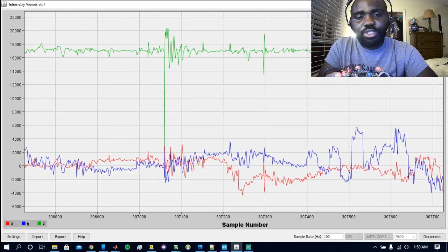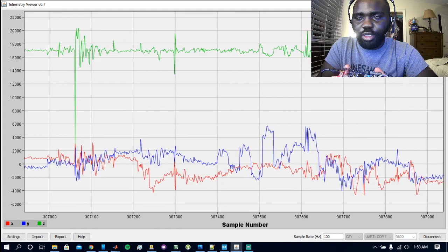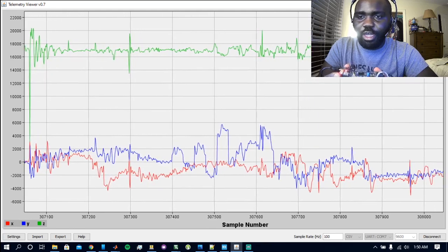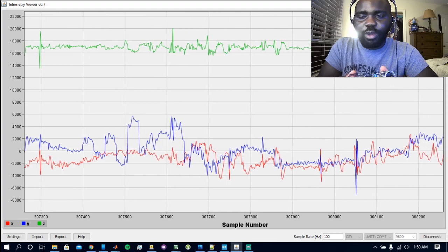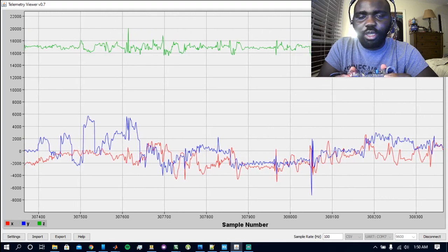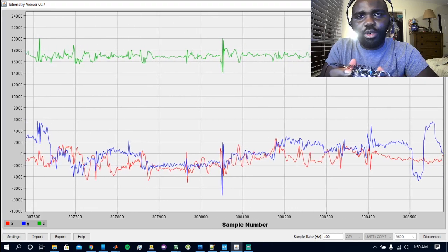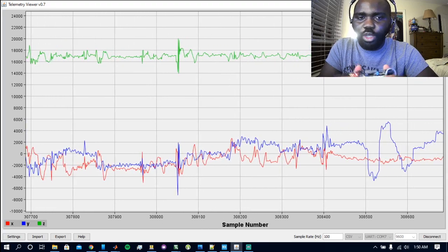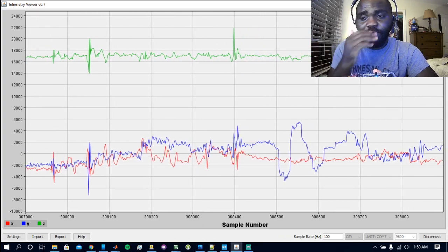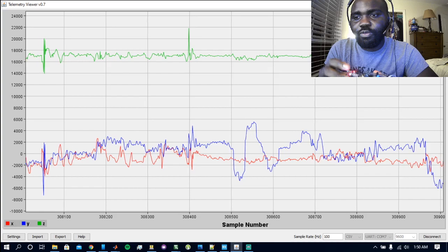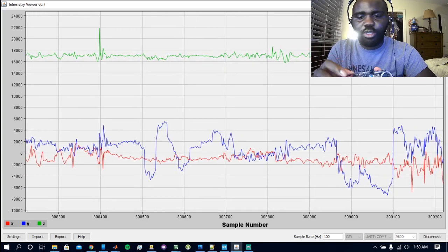But you actually need a gyroscope reading along with the accelerometer reading to come up with much cleaner and nicer positional measurements, to have better and dynamic control of your robot based on its position in space.